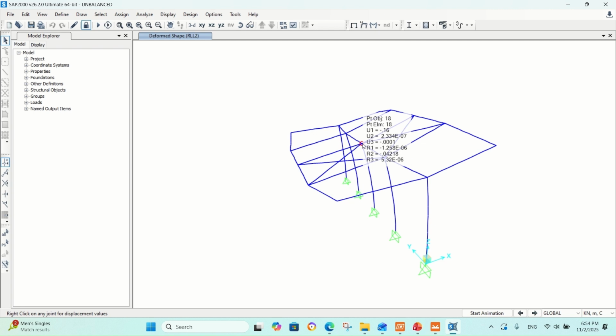Here we have 160 mm lateral displacement of the column. Here we have around 225 millimeter as a vertical deflection. For sure these values are high. Here we want to show the impact of the joint stiffness on the behavior of the structure.